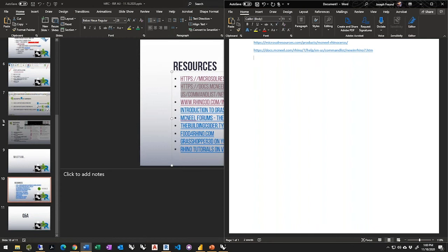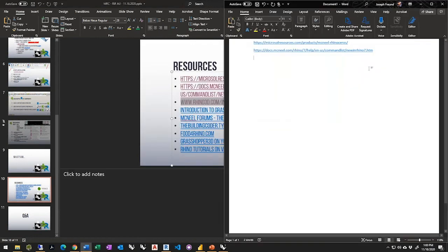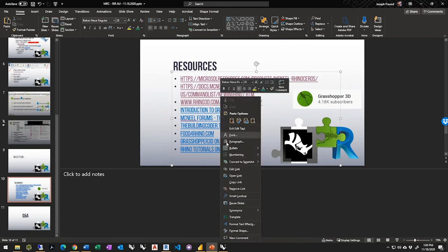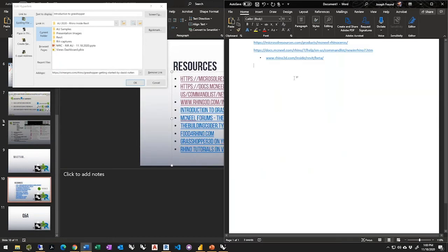Yeah, so Honeybee and Ladybug running in Grasshopper, running in Revit will work. And you can grab the Revit geometry if you want. You can grab the Revit parameters if you want, and use those in the Ladybug and Honeybee workflow. And in fact, the results you can store back on the Revit objects if you'd like, all with Grasshopper.